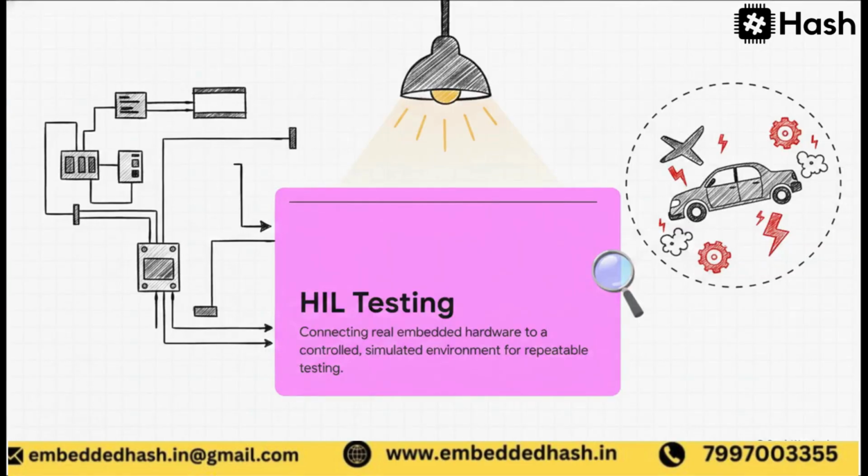Now, to prevent these crazy mysteries from ever making it into the hands of a customer, engineers rely on something called hardware in the loop, or HIL testing. You can think of HIL as the ultimate interrogation room. It involves hooking up the actual physical embedded hardware to a heavily controlled, simulated computer environment. This lets engineers safely trick the hardware into thinking it's flying through extreme aerospace turbulence or driving down a snowy highway, reproducing incredibly complex real-world faults on demand in a lab instead of waiting for a dangerous failure out in the real world.